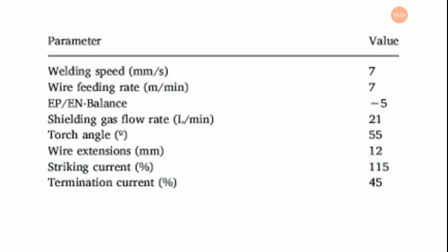The significance and percent contribution of the process parameters for multiple performance show that frequency is the most essential parameter, and it is also found that interactions, especially IP into IB into S, are most significant in determining utility values. So interaction consideration is most effective in analysis. The validation experiment confirmed that the adequacy of the utility value model is justified. It is found that the proposed model based on the Taguchi approach and utility concept is useful and provides an improved solution for multi-response optimization.